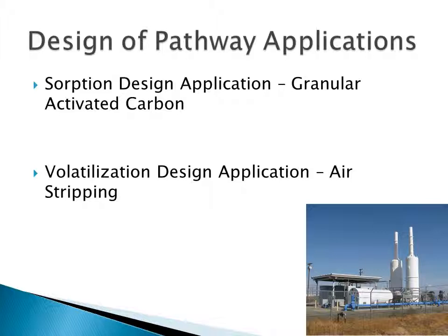So in order to meet typically low cleanup requirements, contactors are often configured in series. The use of 3 contactors in series often provides a low effluent contaminant concentration throughout the service life of the carbon, while also maintaining long contactor runs before regeneration is needed.